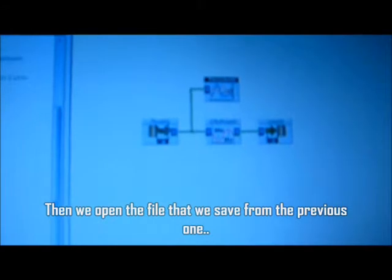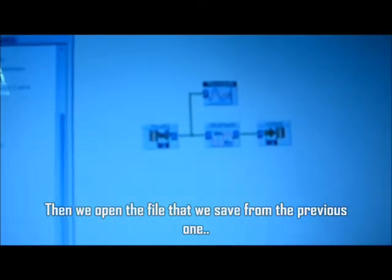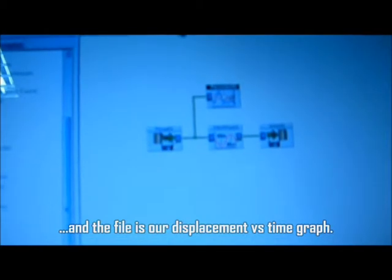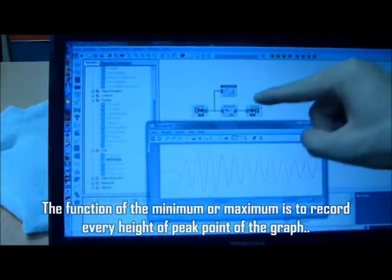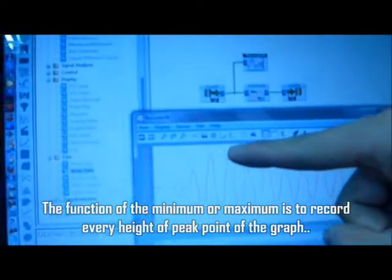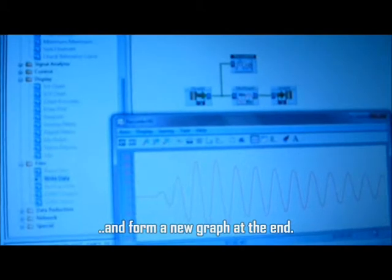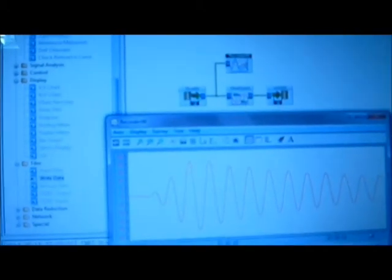Then, we open the DDF file that we saved from before, and that file is our displacement versus time graph. The function of the minimum or maximum is to record every peak point of the graph and form a new graph at the end. Then save it as an ASCII file.